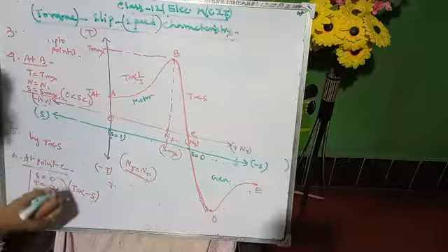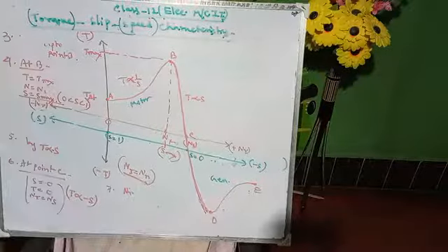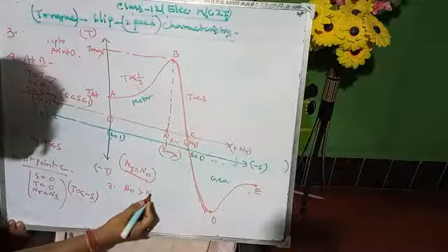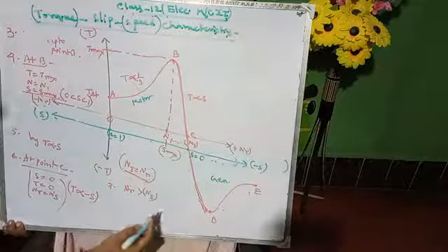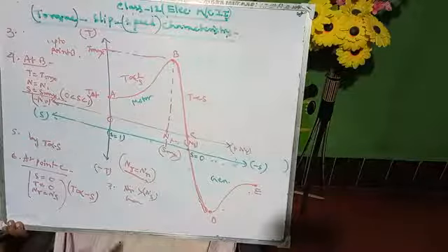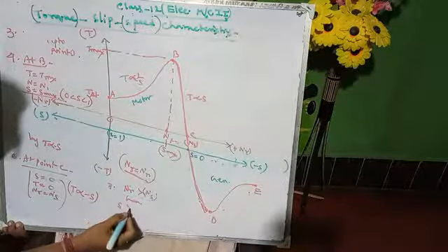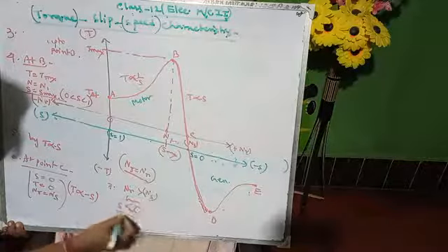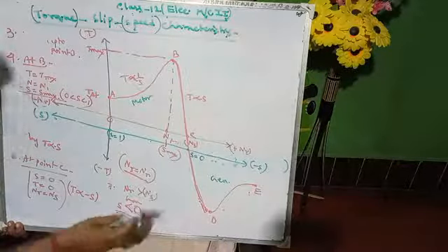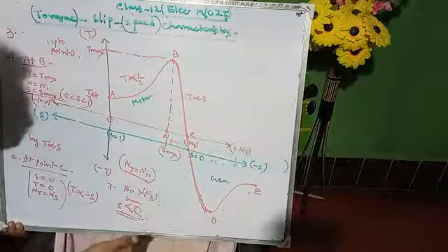So point 7: if we again increase nr, increasing the rotor speed greater than ns, then it will move into the generating characteristics of the machine, where slip is less than 0, that is, the machine runs at super synchronous speed.